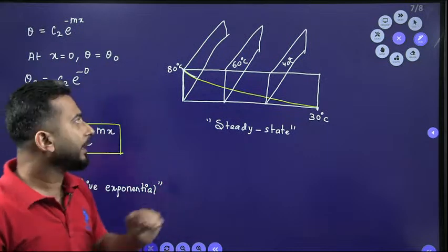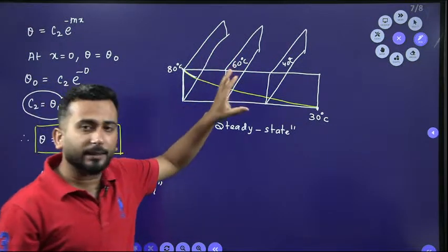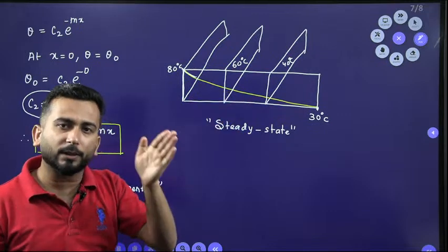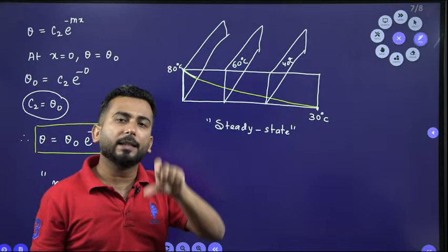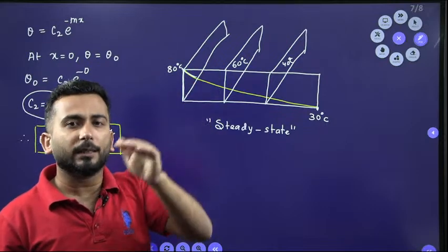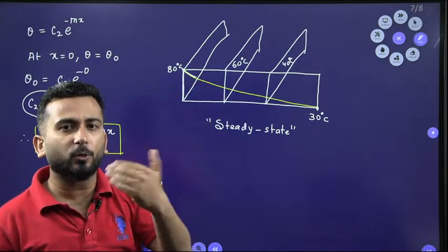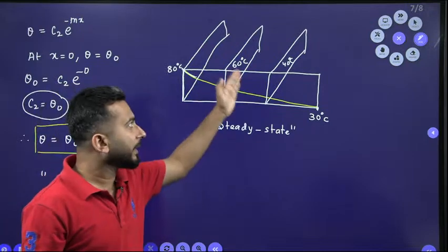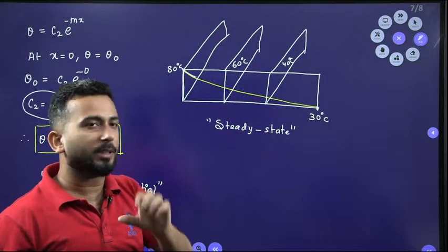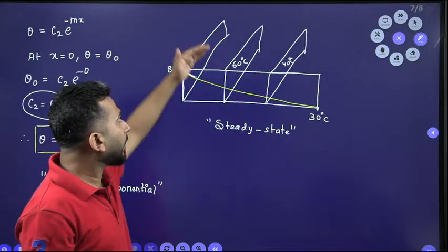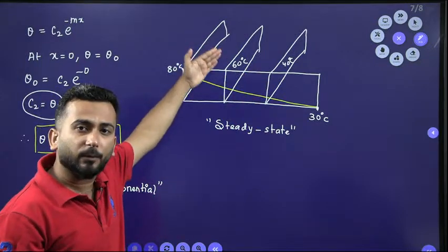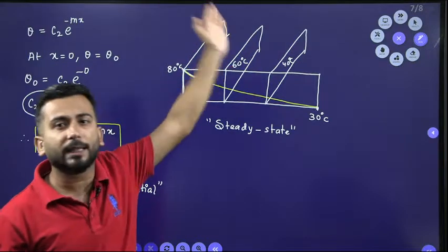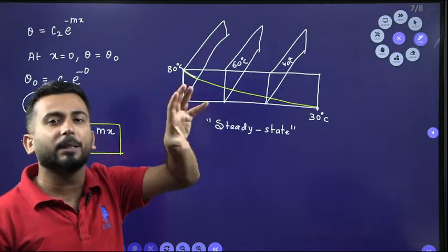I repeat again, at any section if you analyze, heat is getting conducted across the length of the fin and heat is getting convected also. Then only I need to dissipate the heat, na. So that's why we can say that the temperature is also decreasing. Very good. This was our purpose. So what is the total heat which is coming from the base, and that is the heat total that is getting dissipated. So that heat I am interested to know.